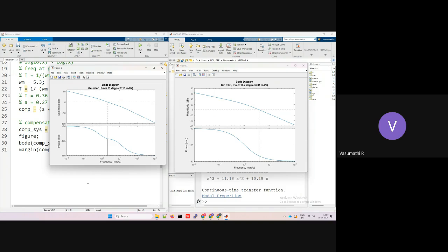And your omega GC value has been given, right? What is omega GC? Omega GC, gain crossover frequency, should be greater than 7.5. So here, if you see, your frequency is 2.09 k, so it is obviously less than 7.5. We have surpassed all the criteria here. So everything is satisfied, and we are claiming that this compensator is a good design.